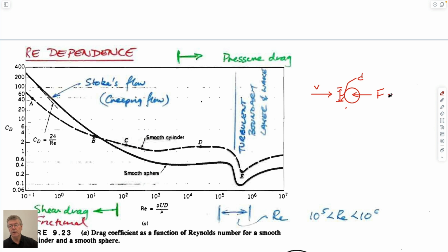So this is what we would refer to also as drag force. And so you measure the force for a given velocity and the fluid's going past it at some given viscosity and density. And you do it at some velocity and you get 1 point. You do it at a higher velocity, you get another point. You do it at a higher velocity, etc.